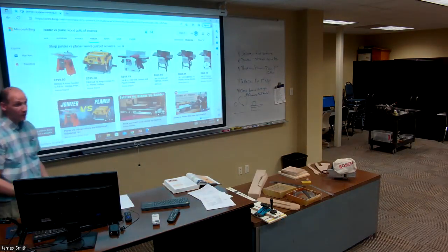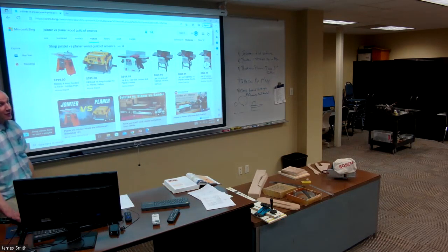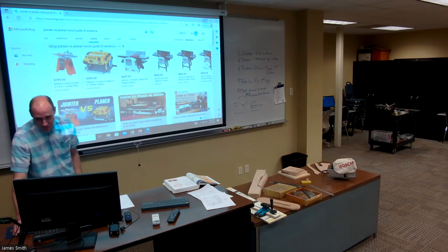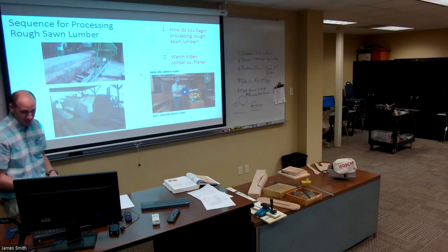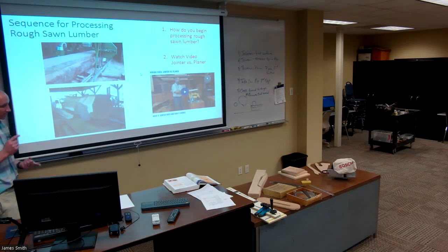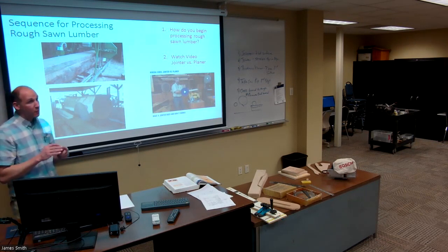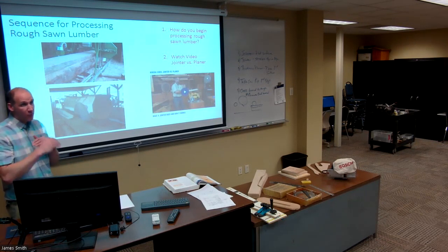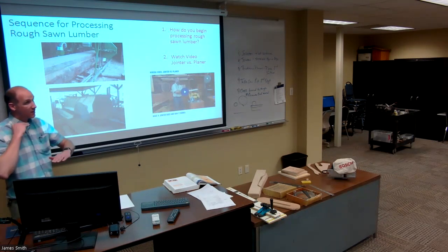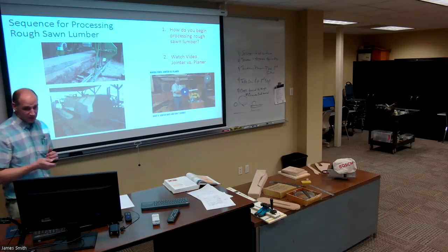Okay, I got that. I was really impressed with that. As a teaching tool, oftentimes it's hard to create those visuals as you're talking about them. But just by way of review, the planer will remove material and create a specific thickness. One other thing too that I've been told, and I think is true, is they create parallelism. So if you have one side that's flat, the other side will be parallel to that. So that is also true.